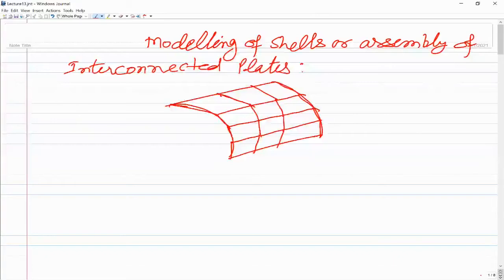But here, because the different elements are in different planes, the transverse displacement of one plate will cause in plane displacement, that is displacements of the middle surface along x and y, in the other element. So now for this case, we want to use the displacement field.